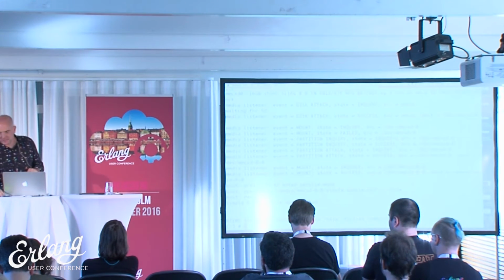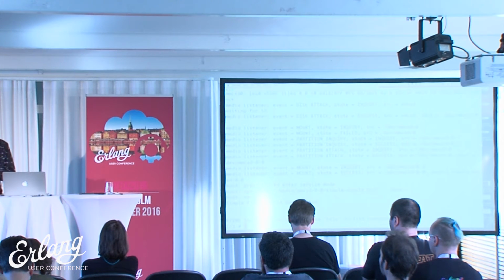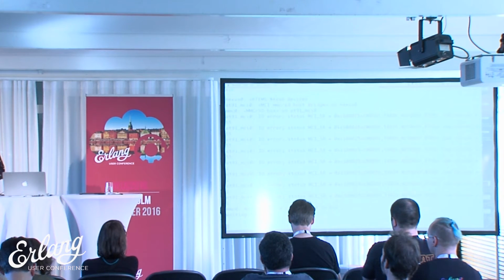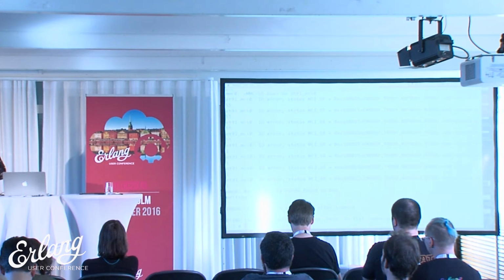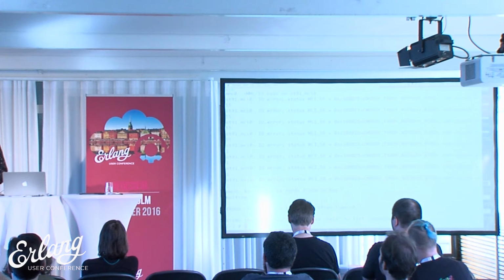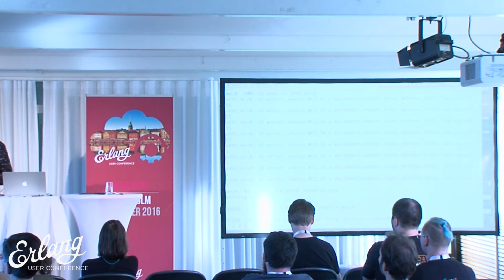So let me show you that something is actually done on the SD card. Let me take out the SD card and push reset again, so it flashes. Now it's red blinking, no SD card. That's actually a bootloader error. And then let's put in a different SD card. That's a different demo. And boot it.